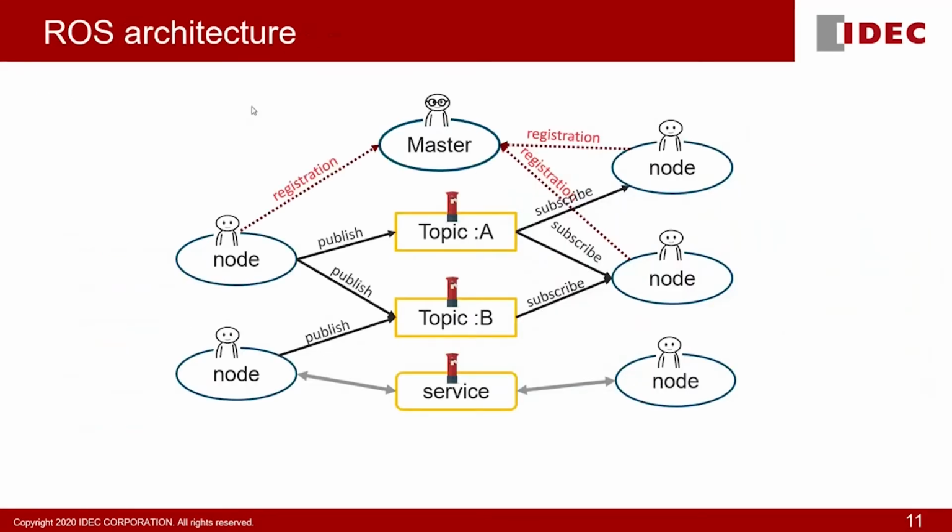Now to understand the architecture of ROS: it consists of a master node and other interfacing nodes. Each and every node which requires to send or receive data needs to be registered with the master node. All the data or messages are stored in ROS in the master node since the other nodes have registered to it. That means once a node has been established, it has to register with the master.